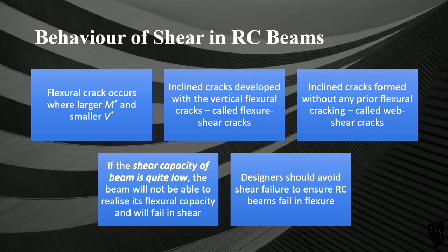So based on that, we will be able to calculate the maximum principal stresses. So when the maximum principal stress equals the shear capacity, you should be able to decide whether you need the shear reinforcement or not.